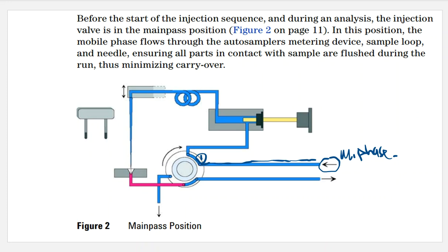All right, so we've already talked about spot number 1. We've also talked about the metering device or the analytical head. So here is the metering device and the analytical head. And as you can see, there is a seal, and that seal can get worn out. And we've talked about replacing seals. The way that we replace the seals on the main pumps is the way that we replace the seals on the metering devices as well. We can also have access to that plunger. That plunger or piston is just like all the others. We look for damage, we look for scratches, we look for chips. And if we see any of that, we want to replace that as well. So just like we do on the pumps, this is like a little mini pump. So why shouldn't we do it here too?